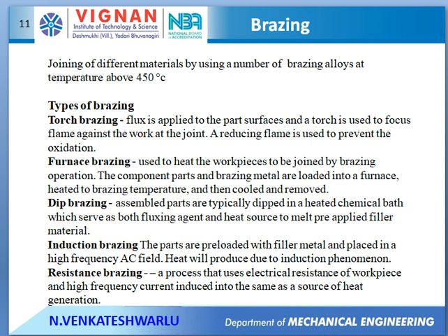Once again I am going to revise. We have discussed the heat affected zone. The heat affected zone is the zone in between the base metal and the weld bead. It is affected metallurgically, and its microstructure and mechanical properties are altered, and the strength of the heat affected zone is less than the strength of the weld bead. That's why we have to reduce the heat affected zone by choosing the proper welding process, like laser beam welding or electron beam welding.